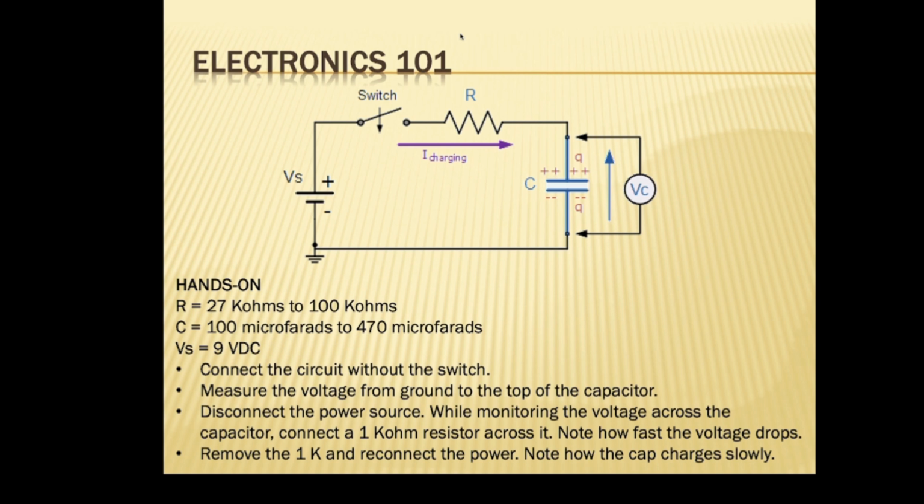You have the breadboard. You should have a 9-volt battery and a 9-volt battery clamp to go on it. We're going to use 9 volts instead of 10. I don't have anything that does 10 volts. And then you're going to need to find yourself a capacitor of some value, at least 100 microfarads or greater. So you're going to need a fairly large capacity capacitor. You may have to dig through the bag to find one of those. And then you're going to need a fairly high value resistor, which I just happen to have a bag of here somewhere.